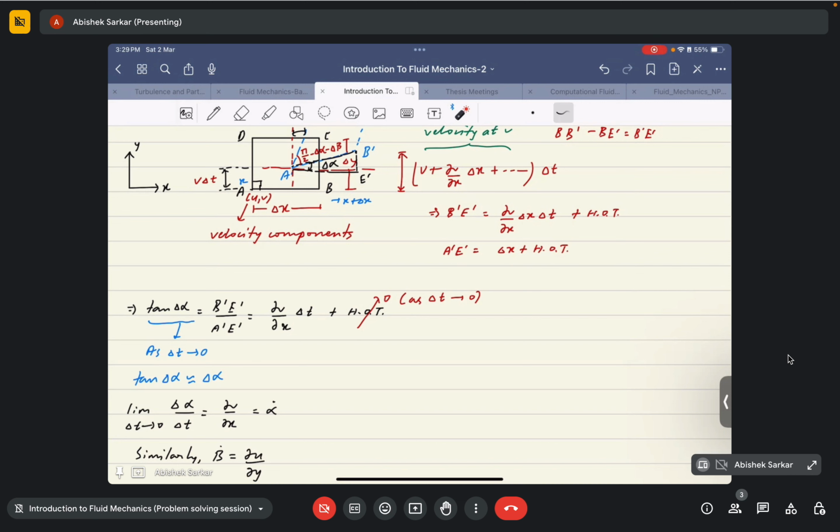Because once the force is applied on the solid, the solid tries to retract back to its initial position, and this tendency of the solid to get back to its original shape results in the generation of internal stress, or internal resisting force, which is termed as stress, right? Internal resisting force per unit area is termed as stress. But in the case of fluid, there is no such internal resistance to the applied force, right? It will go on to deform continuously if the force is applied continuously.